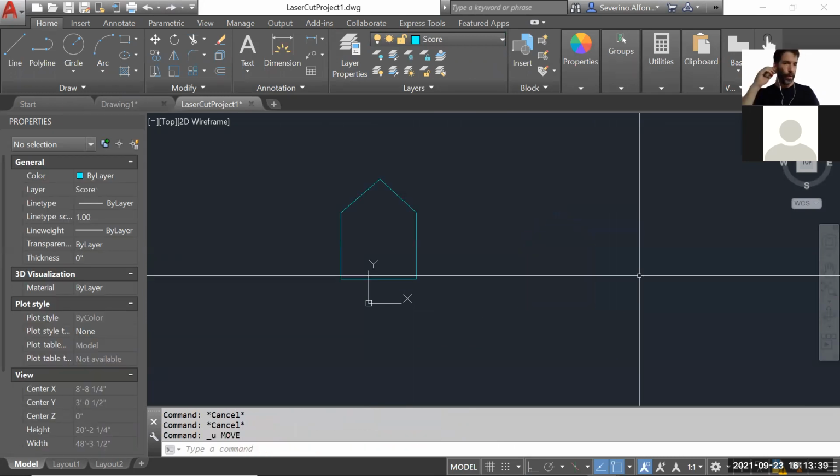So you can do all these things in AutoCAD if it's better for you, but it will be more orthographic. Maybe you can do this in 3D. I'm not an expert in 3D in AutoCAD, but I jumped into Rhino. But in 2D, if you have sections and plans, you can create a polyline around your plan and then just place them, organize them into the laser cutting template. That will work as well.